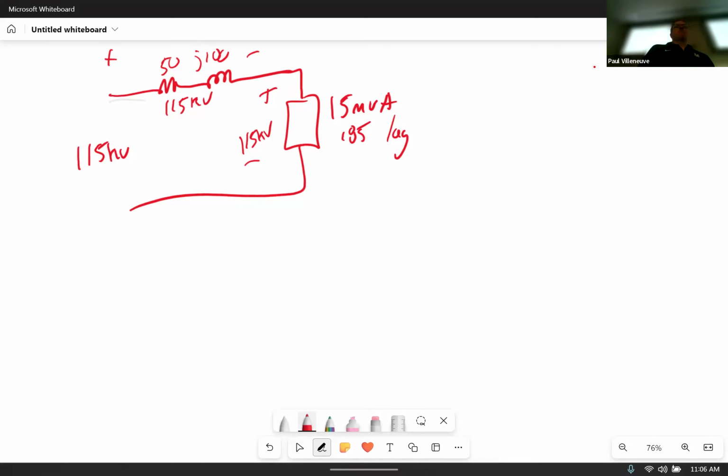That's 0 volts on the load. Yeah, if you put 115 kV drop over here, how much power are you delivering to your customers? None. So your transmission line is a nominal rating of 115 kV. There's no way you should be dropping anywhere near close to that voltage. If you are, why run the transmission system? Because you're not going to be able to sell any power. So you have to put the 115 kV at the load.